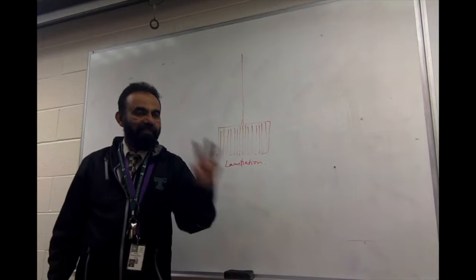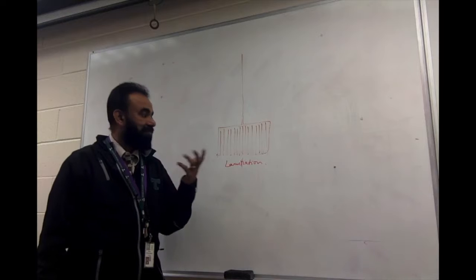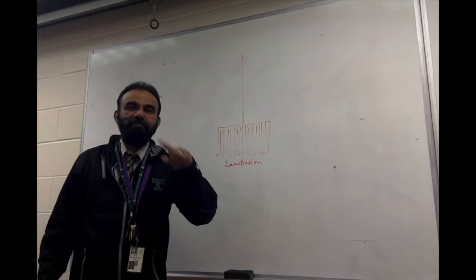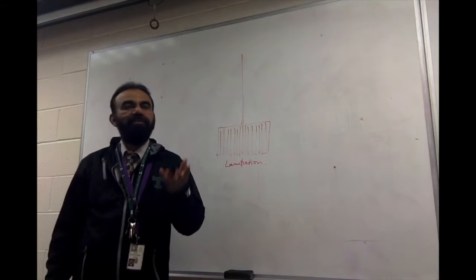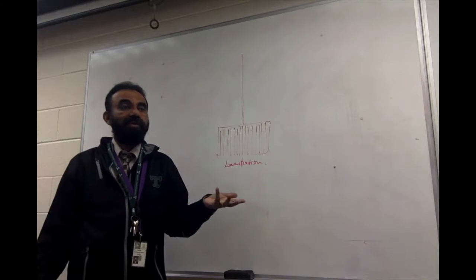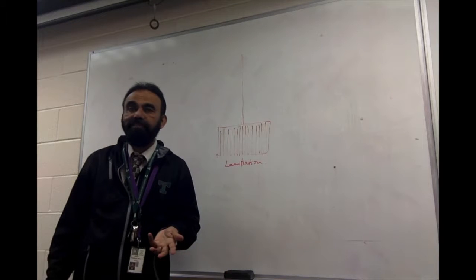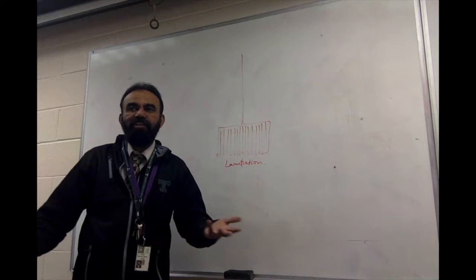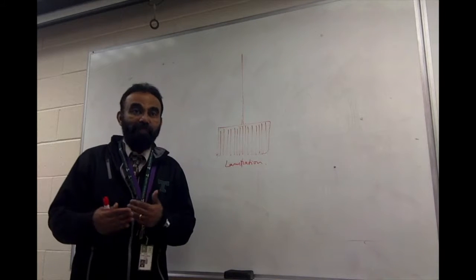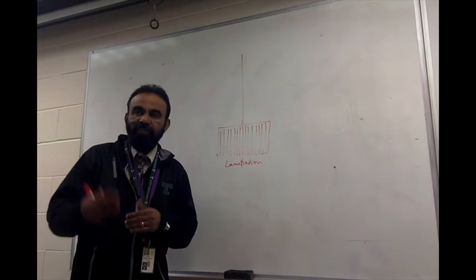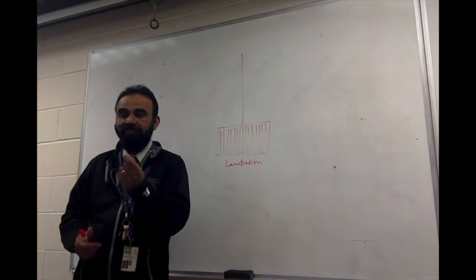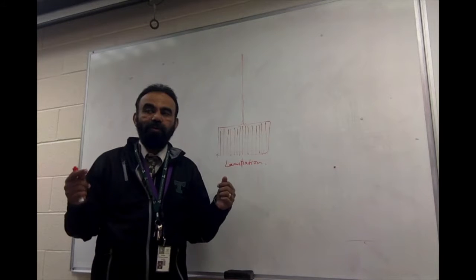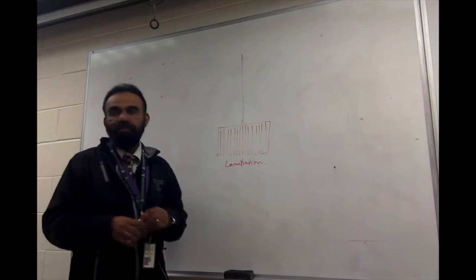So if you have a motor, for example, the motor has a core, right? And that core will be subjected to changing flux. And when the core is subject to changing flux, it's going to have eddy currents. How can you minimize eddy currents? Laminate it. But how much can you laminate? There are limitations to the lamination itself. And when you laminate it, you can cut down the losses a lot, but still you can't rule it out. So that loss is something that is always going to be there.